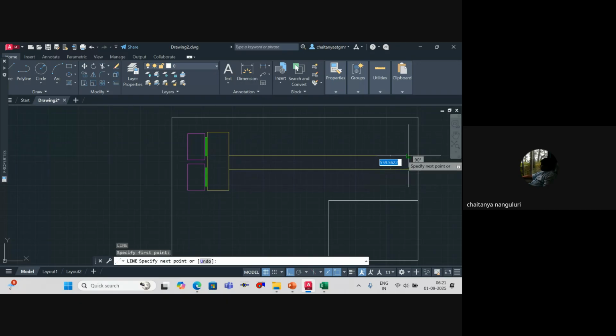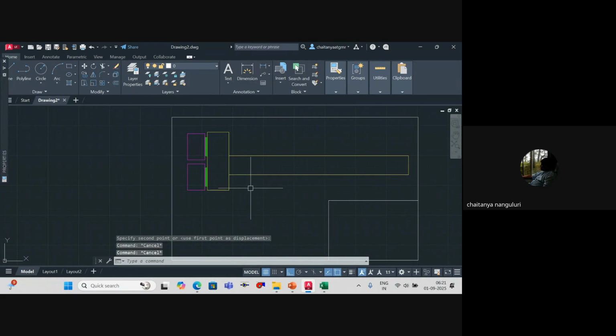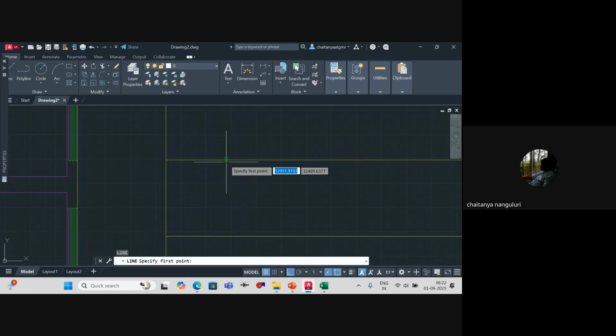So let's say I'm throwing certain air over here. Let's say this is open space, so I don't require any collars. Let's say this is open ducting, like a UPS room where no one really cares about aesthetics. So I need not even have a false ceiling. If there is no false ceiling, I need not throw air only to the bottom. I can even give side throws as well. So for that reason, I'm giving a column, let's say. Don't worry about dimensions, I'll teach you sizing later. This is just for explaining all the components.